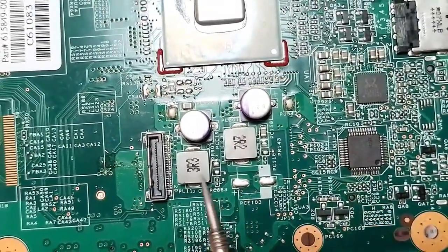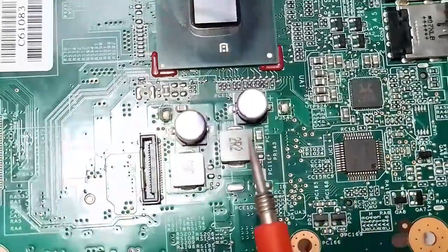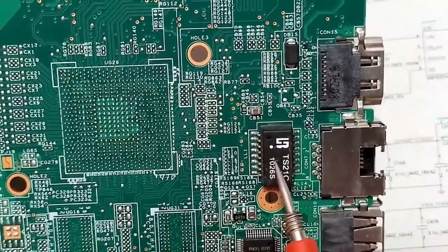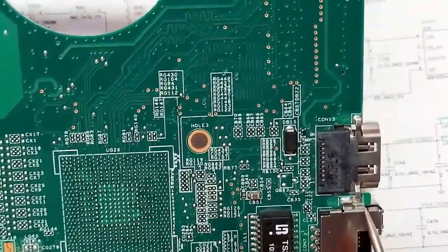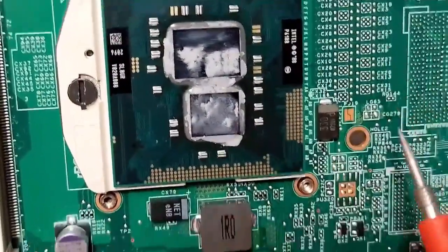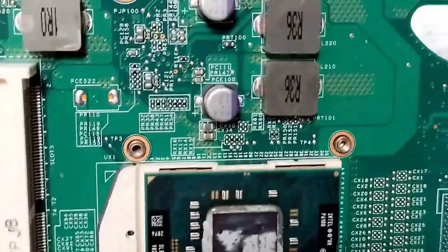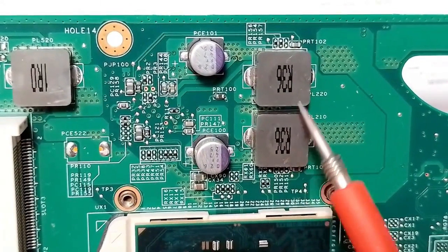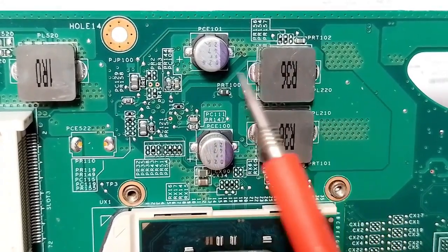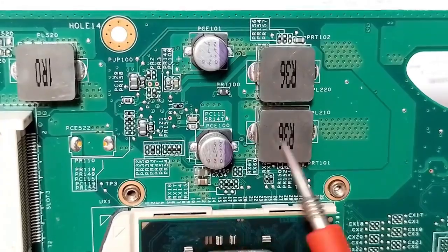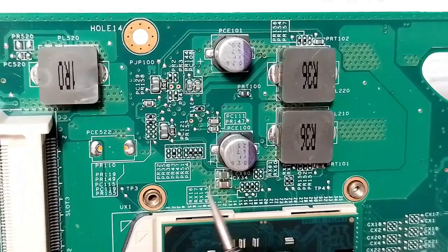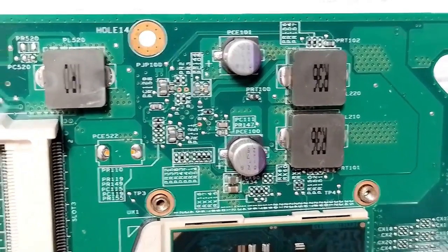By looking at all components in the motherboard, including ICs, capacitors, inductors. This IC basically is the controller for the RJ45. Okay, we have here a crystal oscillator. So over here, we have the CPU. This is basically the CPU circuit where we have these inductors. So each inductor means a channel. We have here the first channel, and this is the second channel for the CPU, okay? So we have here several capacitors. So all these components are good.